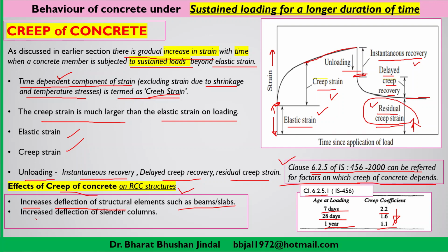It will increase the deflection in slender columns. As for pre-stressed concrete, which is not currently in our scope but just for the purpose of knowing, there will be some loss of pre-stress in pre-stressed concrete due to creep. So creep of concrete is a very important factor which we have to understand before designing any RCC structure.